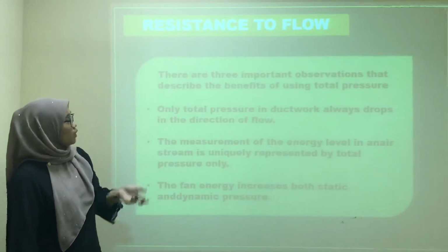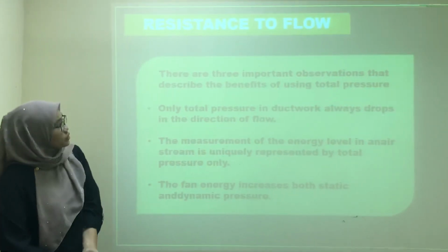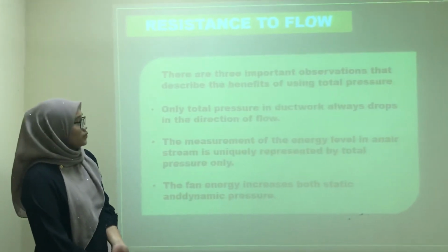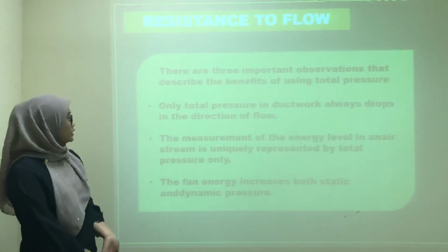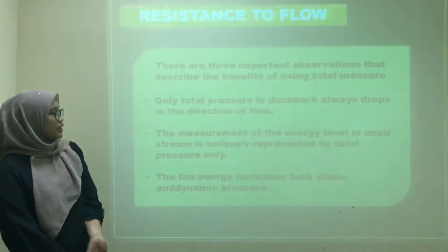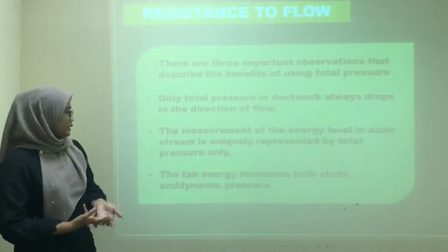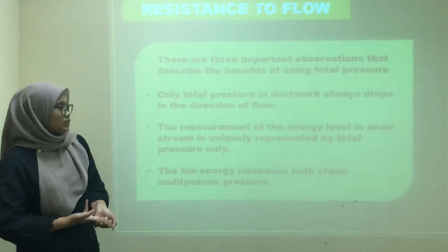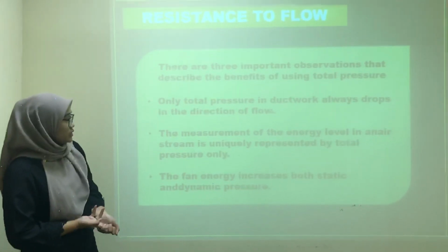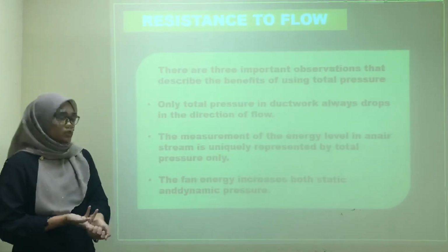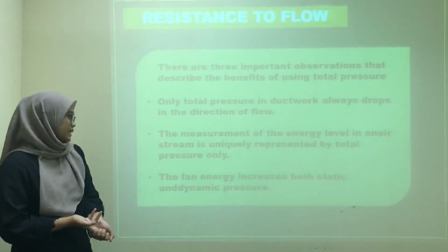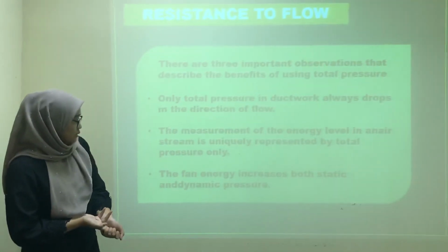Resistance to flow. There are three important observations that describe the benefit of using total pressure. First, only total pressure in ductwork always drops in the direction of flow. Second, the measurement of energy level in an air stream is uniquely represented by total pressure only. Third, the fan energy increases both static and dynamic pressure.